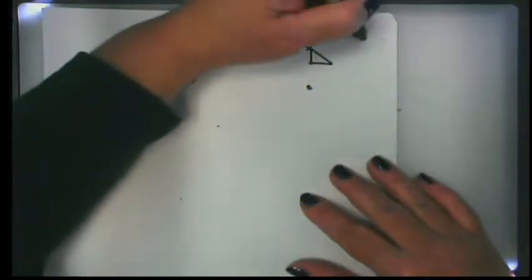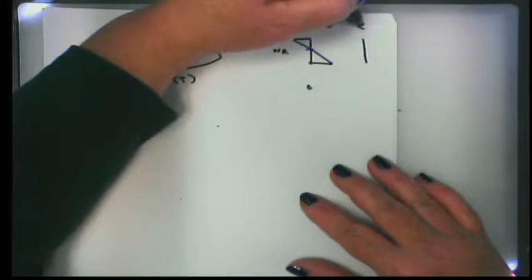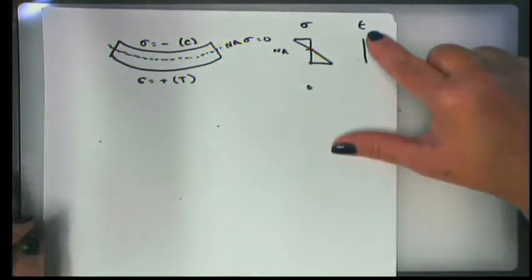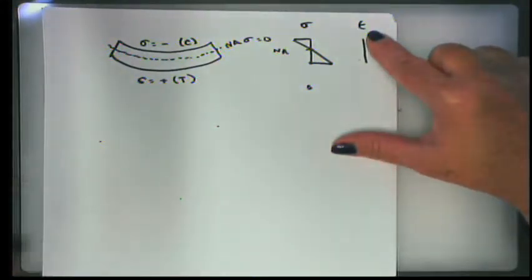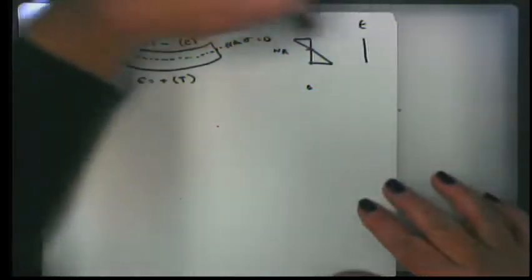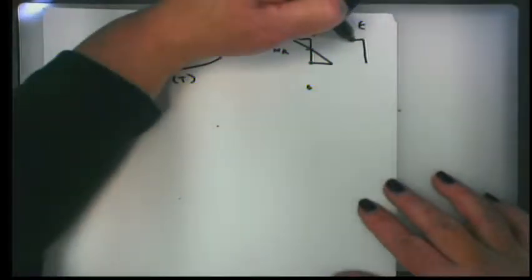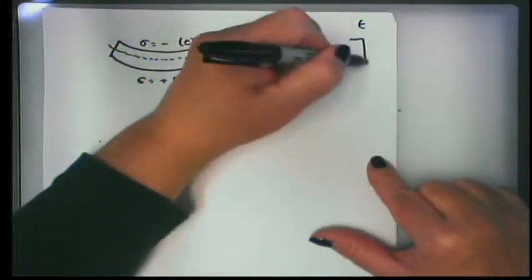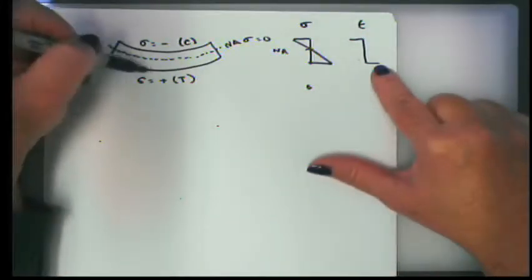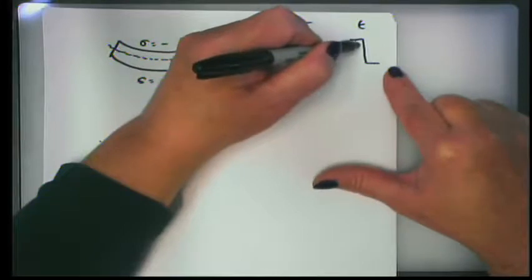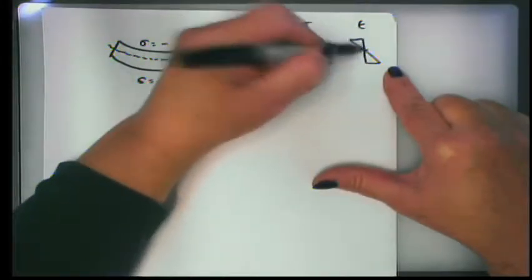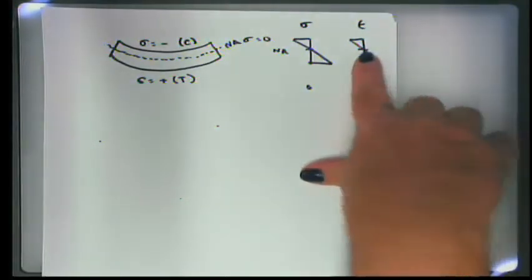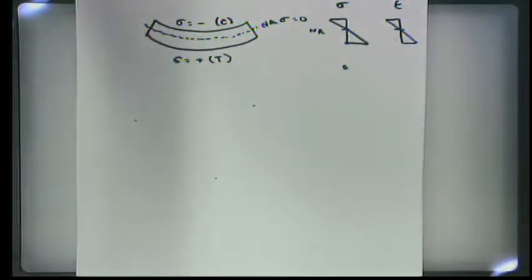At the same time, if we look at epsilon, which is the strain or the fractional change in length, we will have the most change in length in terms of shortening here, and the most change in length in terms of elongation here. And once again, that is a linear relationship. And at the neutral axis, it's equal to 0. So it's very, very true. Absolutely. All right.